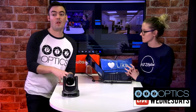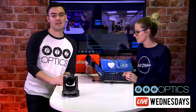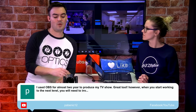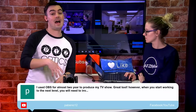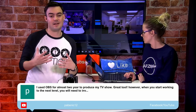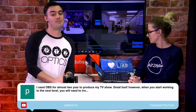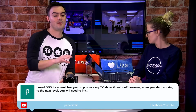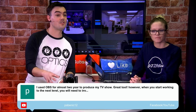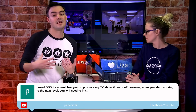amount of latency. So what I tell customers is, knowing that the camera has 60 milliseconds, which is an amount that almost every camera has, that's when it becomes important to buy high quality capture devices, higher quality distribution amplifiers, HDMI splitters and things. If you're using the least expensive one that you found on Amazon, that's probably the weak link. And there's a reason why AJA capture cards are twice as expensive as a Blackmagic card, because it has lower latency and it's built for broadcast and these types of things.